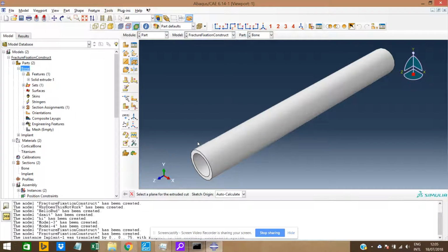So I'm gonna do it with you, and I select the plane for the extrude cut. So that's what I forgot. I have to make a plane first, which is going to be an offset from, as you can see here, the X set plane, the plane defined by these two orthogonal directions. So the X set plane, and for now I'm going to make it 0.